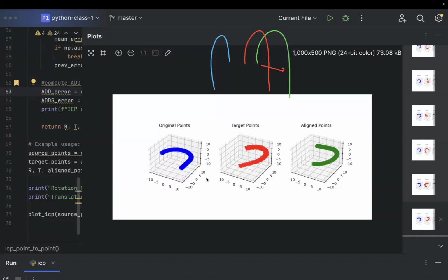I'm telling you this because you probably wouldn't come up with the idea, but if you have a machine learning system like an object detector, you could figure out how the object is more or less posed, but not precisely. So you can have a two-stage system: a non-precise but intuitive way to find out roughly what the pose is, and then use the algorithm to refine it, to put it really millimeter perfect into pose.